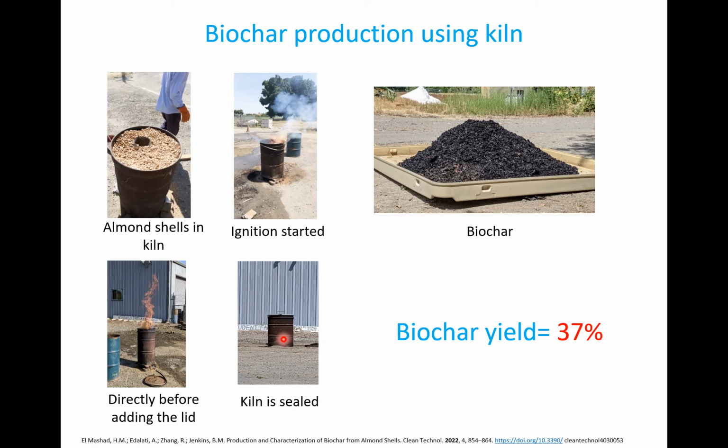So basically, after the initiation of the reaction, you would take off these bricks, so there is no oxygen anymore going through the system. If you look at these tubes here, this is just to distribute some air through the system so that this dense biomass can be exposed to the heat from the ignition process. After this time, you can put the kiln down